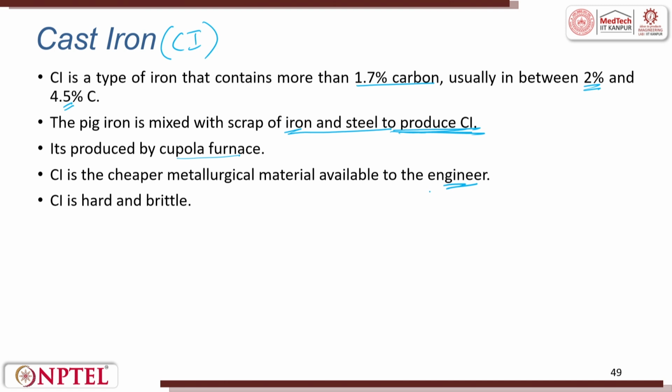Stainless steel and the like need refinement. In the process of generating iron, from pig iron to cast iron, they all go through that. When carbon is reduced more and more, or refined more and more, you get mild steel, low carbon steel, and stainless steel. Cast irons are hard and brittle, so they will always be used at the base, where there will not be much elastic load or fatigue load on them.